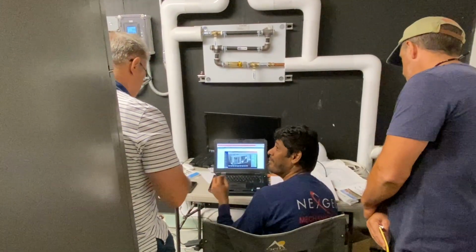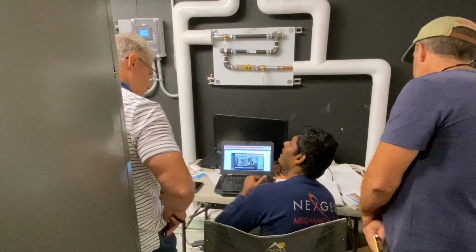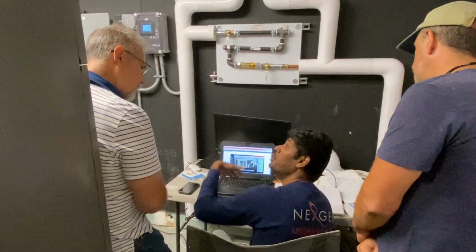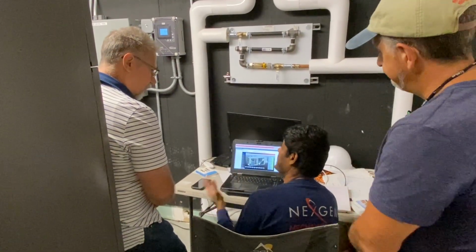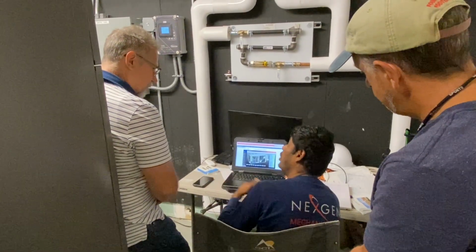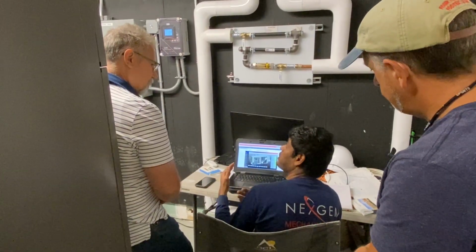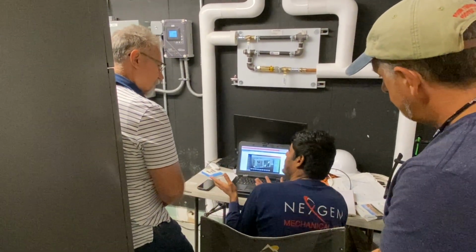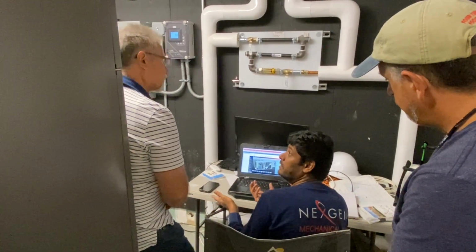Basically, it's a duct static set point, but we are trying to increase or decrease it proportionally based on the load on the VAVs. For example, if 70% of my VAVs are more than 90 percent open, which means most of my primary zones are satisfied, then I'm going to decrease the static to conserve energy.